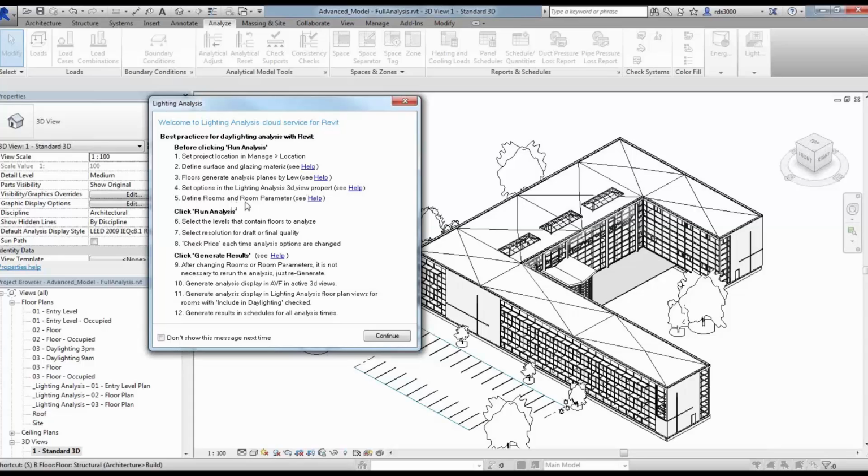And then rooms, it's not actually required to define architectural rooms in your model, but if you do define rooms, rooms are used to define LEED regularly occupied spaces. It's also used to summarize the data in the rooms table about how your performance is on a room-by-room basis. And rooms are also required to generate the proper results for the LEED submittal.